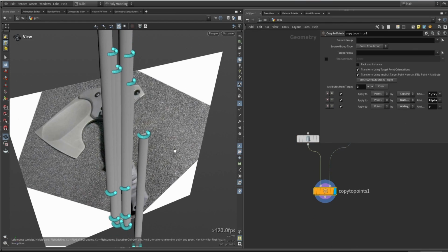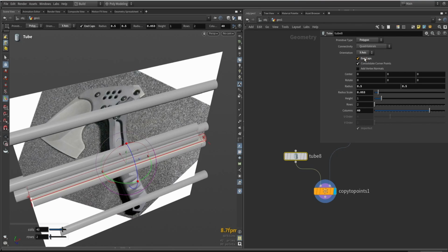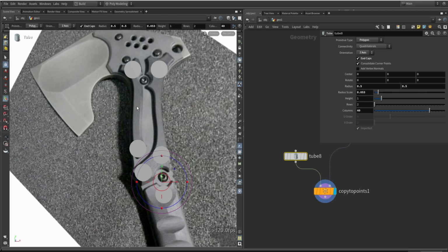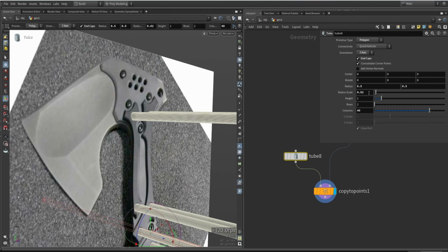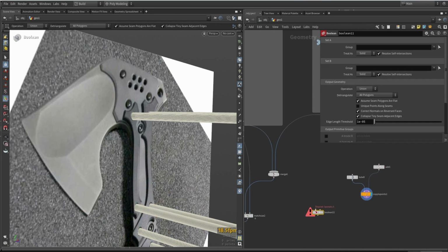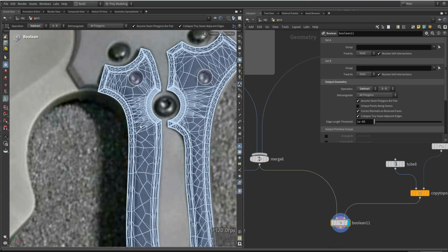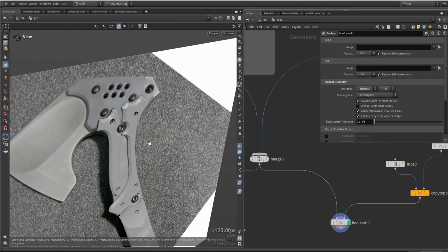You can see we also need to rotate this in a different axis. So in the orientation mode, let's see the orientation. So this will be the orientation. This needs to be way smaller in scale. So I think, yeah, in this case, that sounds good. Maybe a little bit less. What we want to do with this then is, of course, do the subtraction with the boolean, subtracting these, essentially the holes in there, so we have room for a bolt.